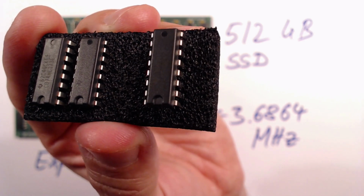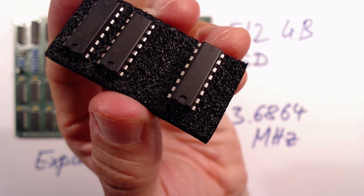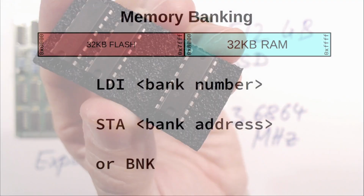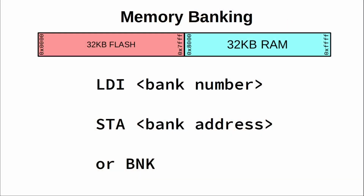A leaner way could be to use a free control line of our CPU's control word to build a dedicated instruction that moves a value into the bank register. From a software perspective, LDI bank number loads a bank number into the A register of the CPU. With the first approach, STA bank address moves the content of A into the bank register by memory mapping it to a bank address, whereas with the second approach, an instruction bank moves A into the bank register. Both approaches have their pros and cons. For my own CPU, I have decided to use the second way.